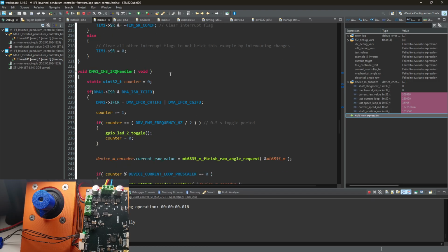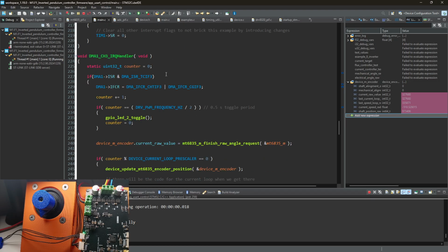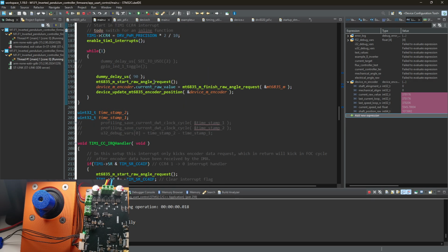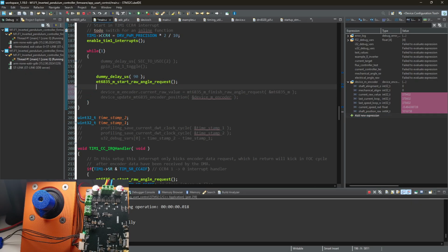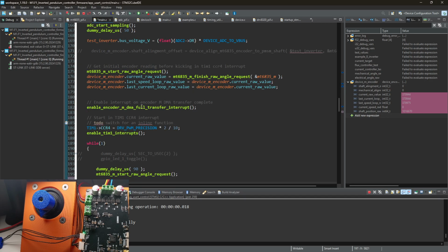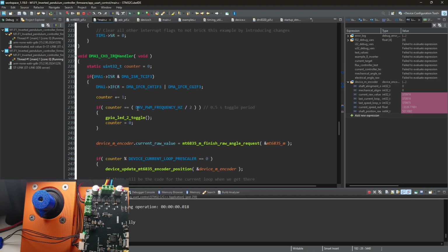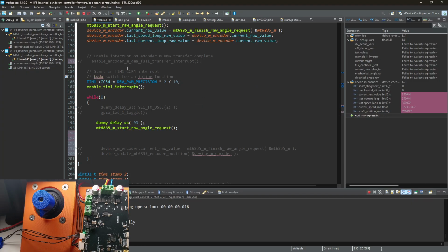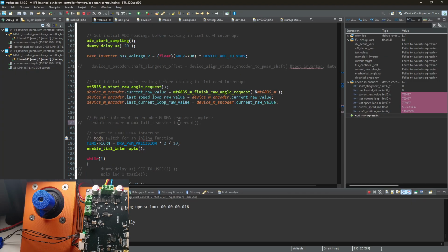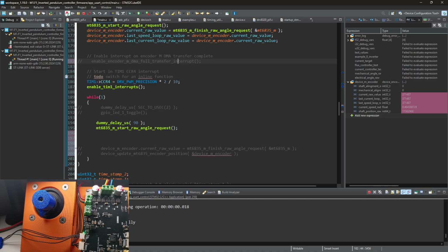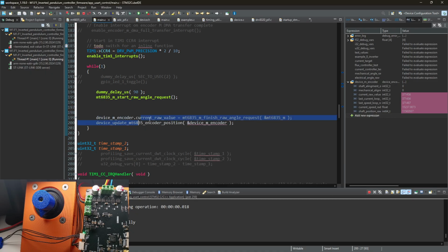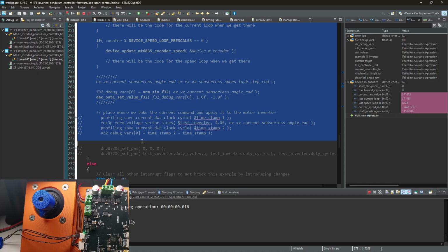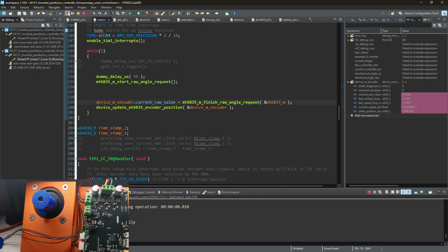And now thinking about it, what I think is that we use different functions. Let's, instead of this, use the functions that don't use direct memory access. And let's not enable this, because actually this interrupt is random. Oh, but it enables only interrupts, so we should have removed... Like, let's remove this line only, and let's test without it, because this interrupt was actually fired multiple times, and it's not supposed to be fired. So let's test without it.